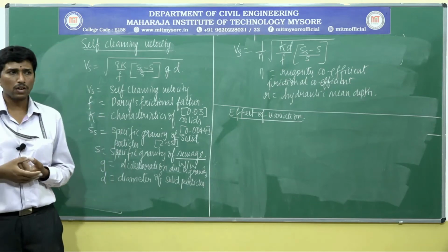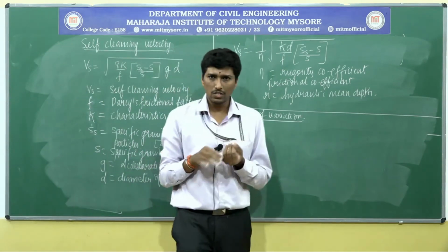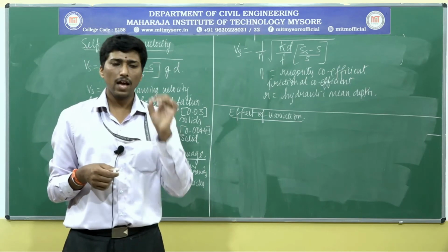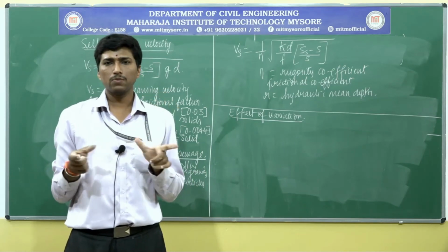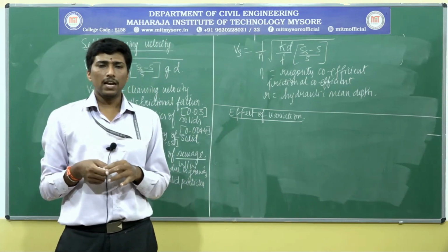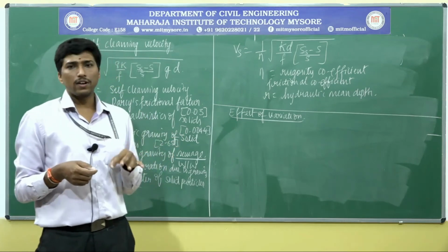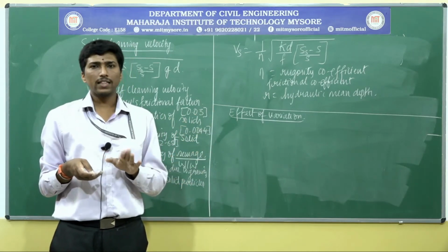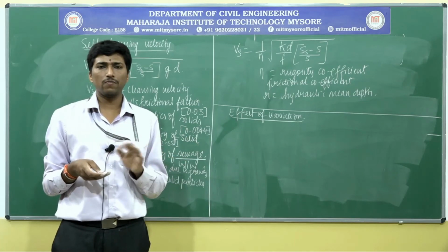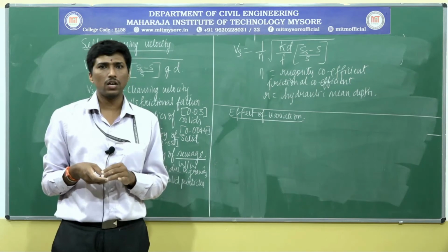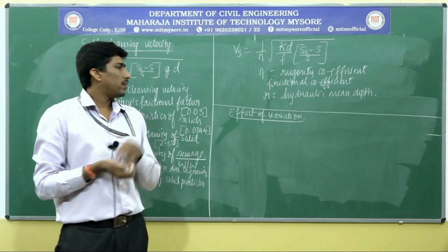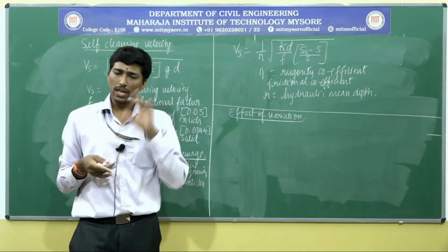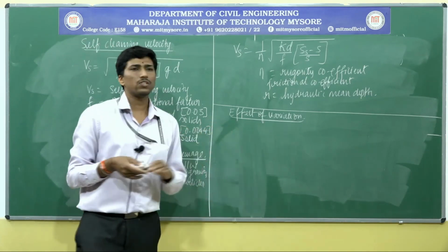How it mainly depends upon the diameter of the particles which are present there. Normally the particles arising from each and every house are measured in millimetres, not in metres, mainly the fecal matter and so on. In the case of stormwater drainage, the pebbles or any other things will in turn get carried away. I am not saying that in the case of residential areas. There are some cases, in residential activities or in newly built houses, where grit materials will tend to flow along with the normal wastewater flow in the sewer systems. So we are taking this into consideration. We need to check what the variations are.